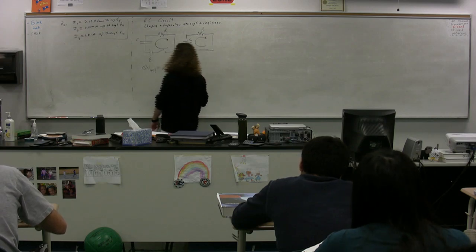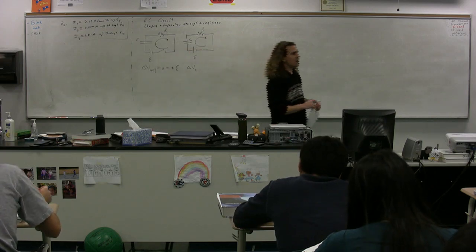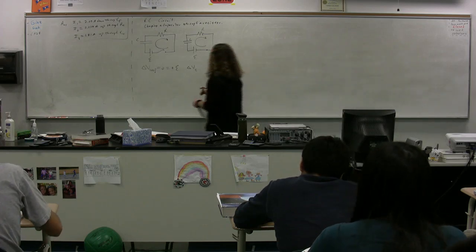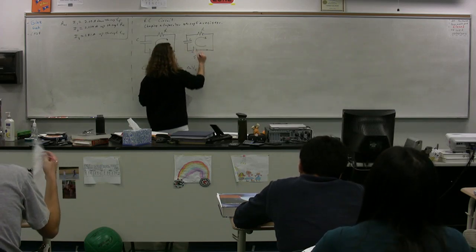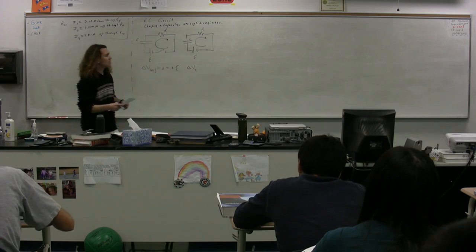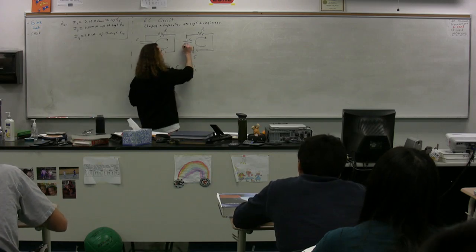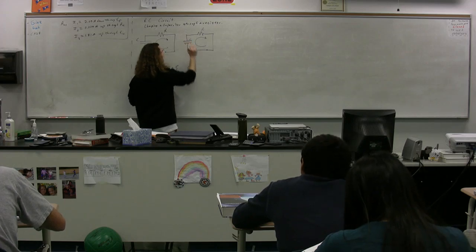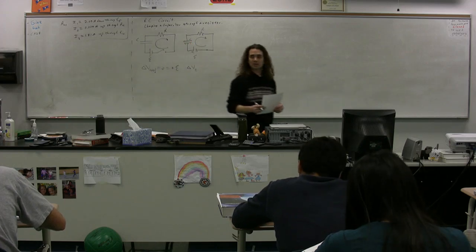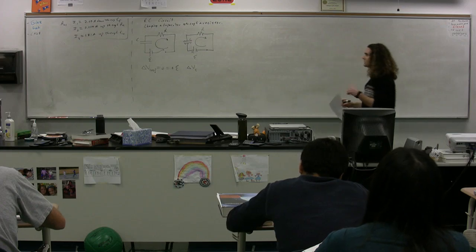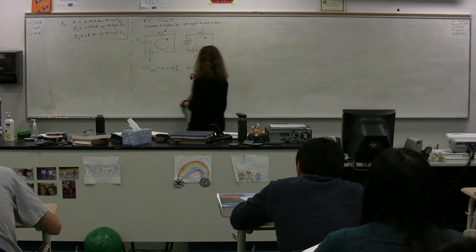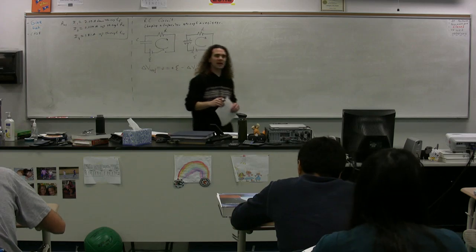The capacitor. So we have to decide whether the potential goes up or down across the capacitor. As time goes by, we are going to build charge on the capacitor. The bottom plate is going to develop a positive charge, and the top plate is going to develop a negative charge over time. Therefore, the potential difference across the capacitor is going to be positive or negative? Negative. As we go from positive to negative across the capacitor, the potential is going to go down.